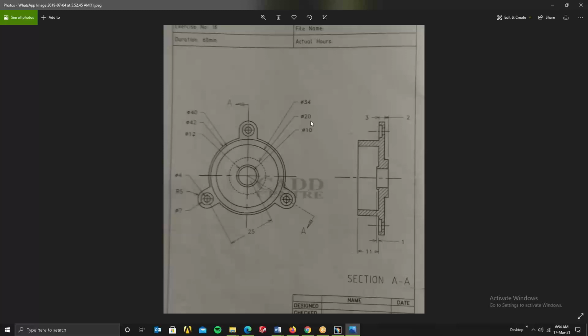I feel like creating circles with multiple pockets will be easier. We could do pockets too, but you could have done that before, if you were doing this model in the previous class. Since we have gone through the revolve command, you can use the side profile to revolve it and then use the hole command to pocket the three holes.